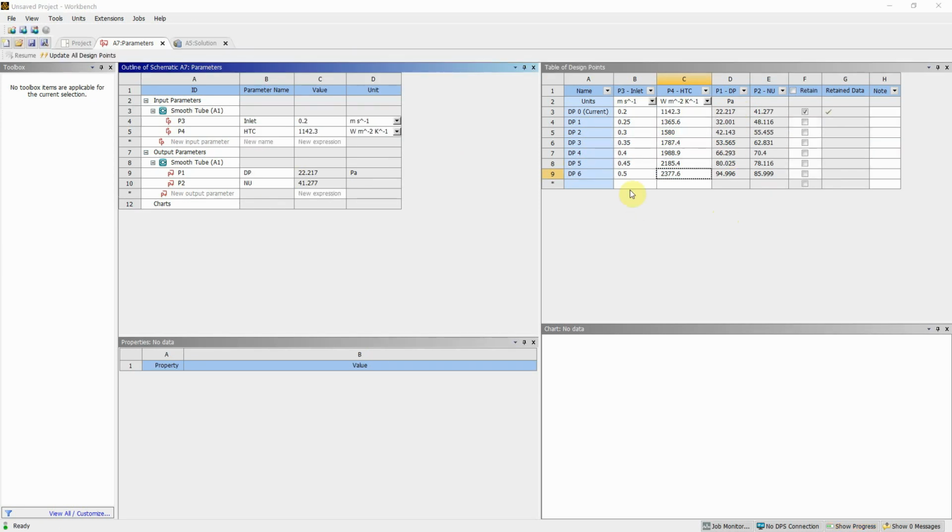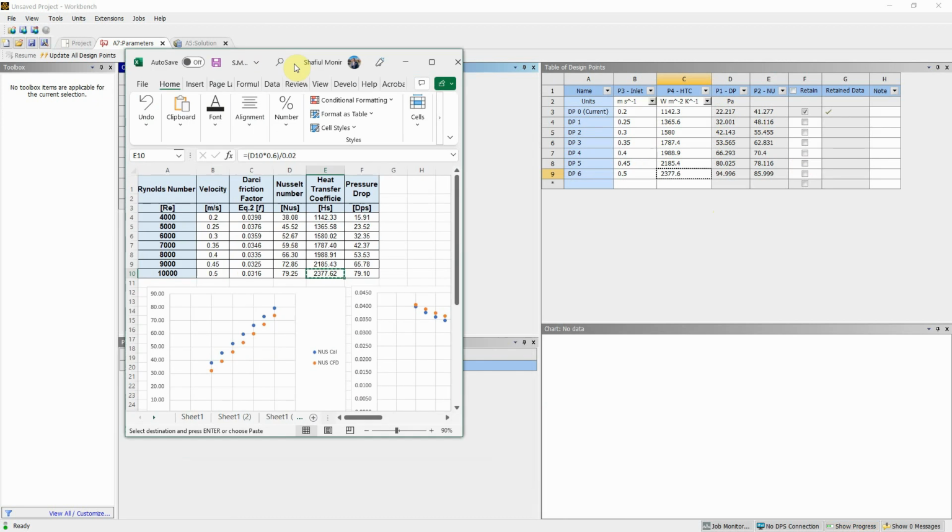Okay, so as you can see here, all the simulations are done. Looking at the results, the nusselt numbers are 38, 45, 52, against 41, 48, 55, and then 79, 85, 78, 72. So it's in good correlation, but it can be a lot closer and better, because remember, once you've got this one validated, you then apply the same approach to the spiral groove.